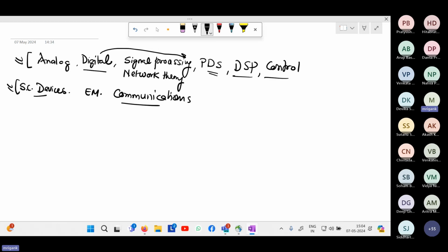They need to be aware, because analog signals, analog processing is very much sensitive to those device parameters. So they need to be more conversant with the devices, device operation, device characteristics, device non-idealities, as compared to digital. Digital people also need to be aware, but analog may need to be more well informed about the device non-idealities, especially for the advanced nodes, advanced MOSFET nodes that people are working on today. So if you want to be an analog design engineer, then you can't leave aside anything.